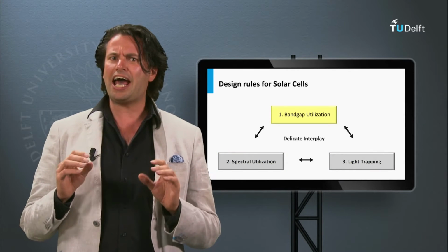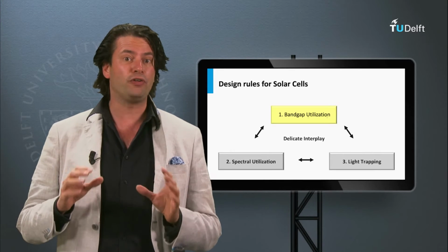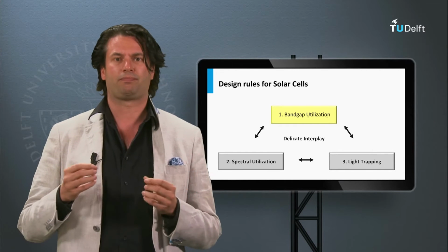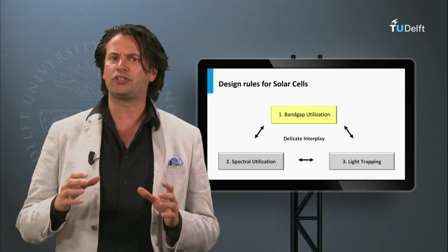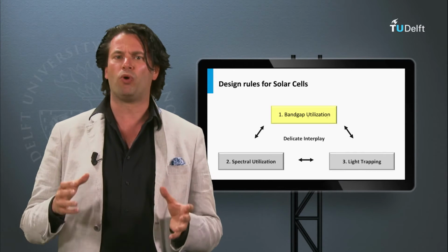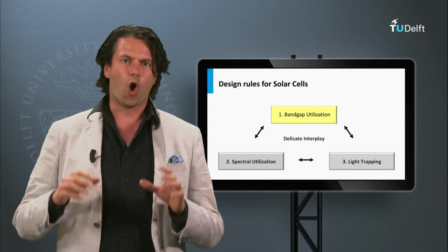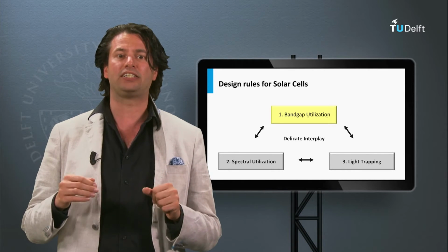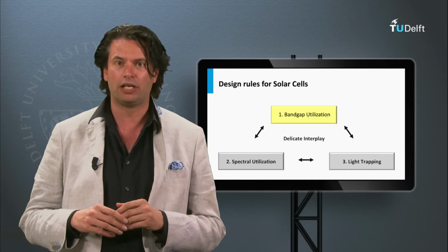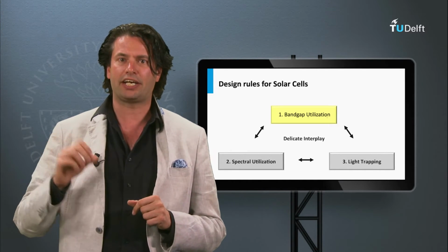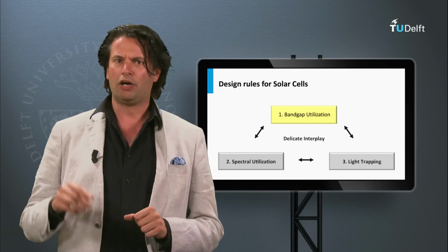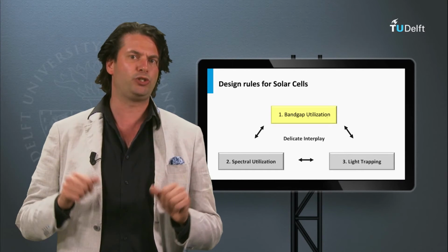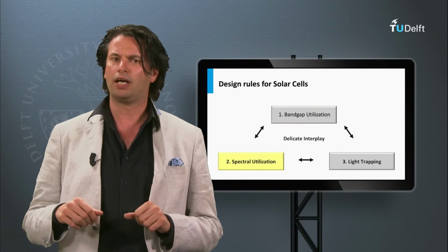First, the real energy used to generate voltage is the product of the open circuit voltage and the elementary charge. Under normal operation conditions, this energy is always smaller than the total bandgap energy. Open circuit voltage is determined by the extent to which the quasi-Fermi levels are able to split, which is limited by the charge carrier recombination mechanisms. We will show that the various PV materials have different recombination mechanisms that limit the utilization of the bandgap energy.